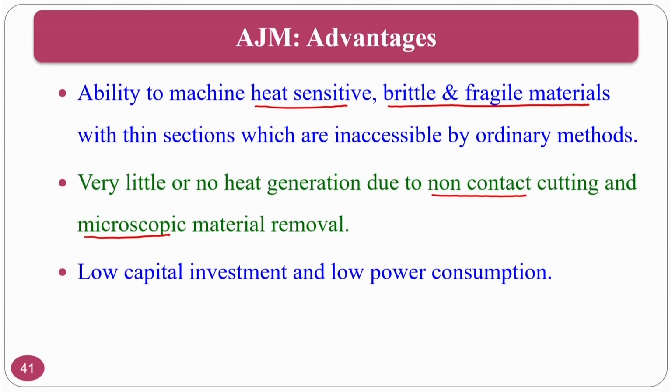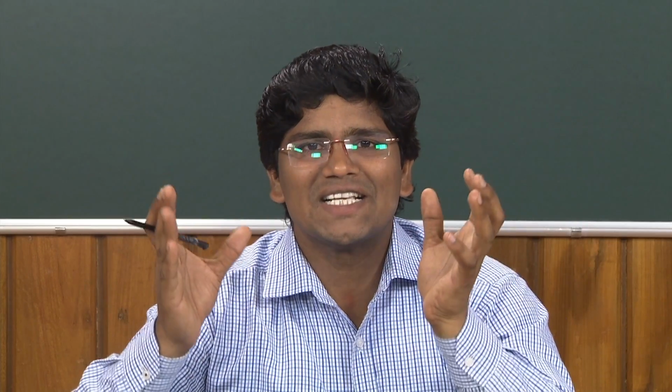Low capital investment and low power consumption. That means you can develop this abrasive jet machining in your laboratory at a very minimal cost. Even if you don't have funding, you can develop it. You need one compressor. Normally compressors are not that costly. You can have different ratings of compressors, and you can get those compressors.